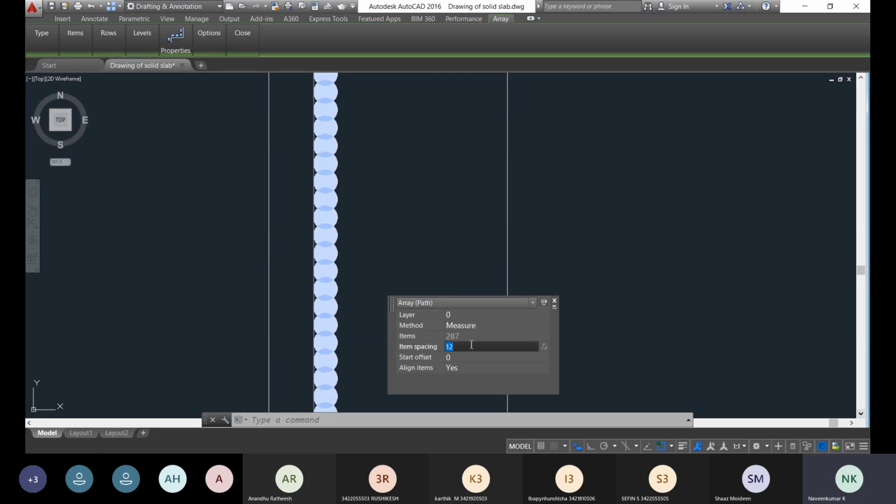For example, from the top to the bottom 500 mm, it is 400 center to center. After 1000 millimeters, it is 350 center to center, and another, it is 200 center to center, and at the bottom 1000 length, it is 140 center to center. So it is different at different levels.